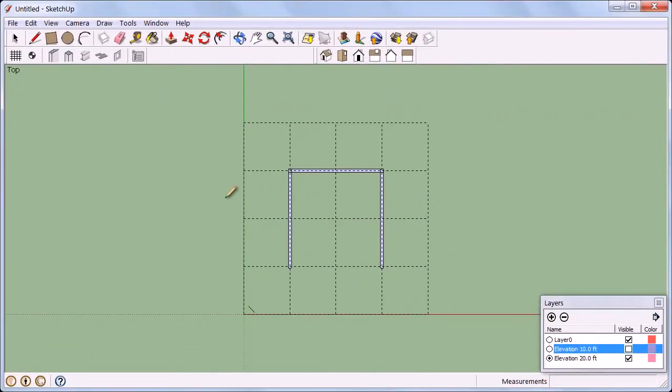In some cases, it might be required to view the level below to provide a reference for new elements to be added on the current level. This is simple in SketchUpBIM. Simply check the below floor on the layers dialog. In this case, you will notice that the elements from the floor below are now visible on this floor to provide reference for new elements. I'll use this reference to create two new columns on this floor.